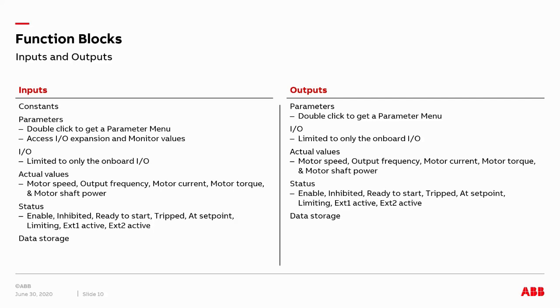Status is essentially, these are true-false type situations, typically telling you that the drive's enabled, inhibited, it's ready to start, tripped, at set point, etc. These are things you can, typically you're going to use them to read, but you can also change the status by writing to those signals as well.